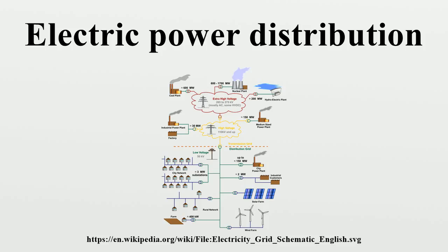Distribution circuits are fed from a transformer located in a substation, where the voltage is reduced from the high values used for power transmission. Conductors for distribution may be carried on overhead pole lines, or in densely populated areas, buried underground. Urban and suburban distribution is done with three-phase systems to serve residential, commercial, and industrial loads. Distribution in rural areas may be only single-phase if it is not economical to install three-phase power for relatively few and small customers. Only large consumers are fed directly from distribution voltages.